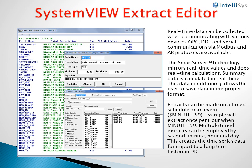Real-time data can be collected when communicating with various devices. OPC, DDE, and serial communication via Modbus and AB protocols are available, and that's actually with the real-time server. The smart server technology mirrors the real-time values. Summary data is calculated in real time.